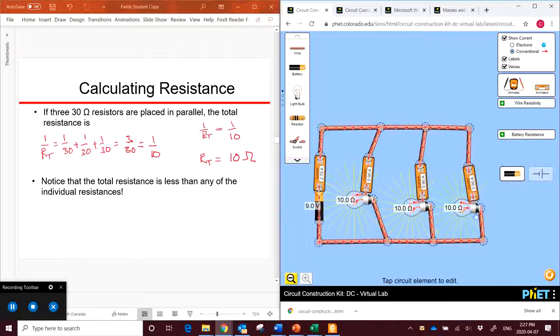Add a third path, same thing. We opened up a third possibility for everything to flow, so we can get things moving faster by adding more paths. So as a result, this drops the total resistance by adding more optional paths for the current to flow.